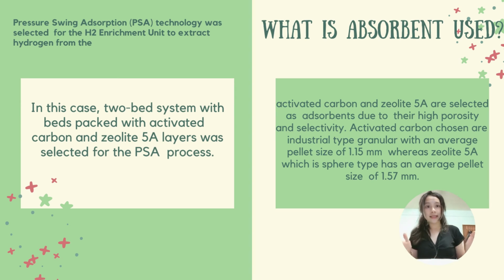In addition, the second adsorbent that we have chosen is the zeolite 5A. And the Langmuir-Freundlich model, by referring to the loading ratio correlation, we know that it is suitable to compute the adsorption energy distribution onto an adsorbent surface that is heterogeneous. With the model formula of q1 equal to (k1 plus k2 T) multiplied by k3 exponent (k4 over T) to the power of Pi, as well as using the overall formula with the denominator and the numerator, we can calculate that the model for adsorption of gas on the activated carbon and zeolite 5A was constructed.